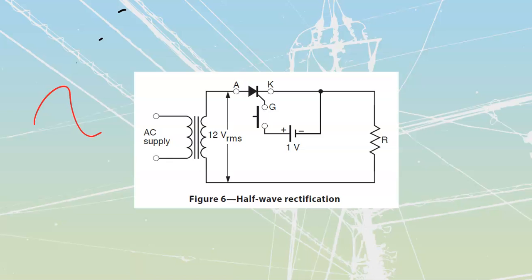So I take a look at my anode and my cathode, and when I do, I see that I've got them forward biased. Anytime that I've got positive, negative here, this thing is going to be able to turn on. And as long as I then hit this little circuit over here, and I know this really bothers some of you, the fact that we've got an AC circuit over here and a DC circuit over here, but you're actually allowed to combine circuits because where does current want to return to? It wants to return to its source.